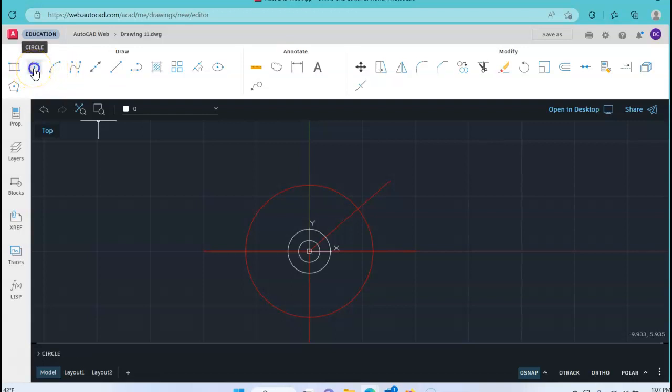So I'm going to just create some circles here again. In this case, I'm going to use the circle at this point. Now, you know from looking at the print that this point is at 3, 0. And I'll place that at that intersection point. And again, this is a 1/2-inch radius, so 0.5, enter. So that gives us our 180-degree part of the slot going this way.